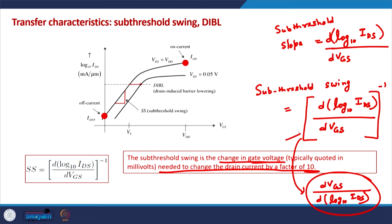So we write it in this way, we do not write it in the other way. This is defined as the change in the gate voltage below threshold voltage, in the sub-threshold regime, that is required to change the drain current by a factor of 10.